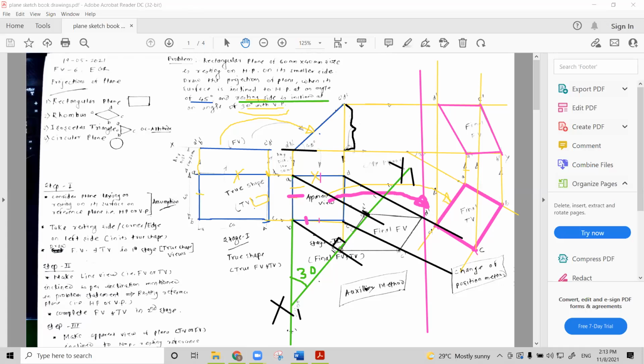So this is what the distance from this point to this point is, nothing but the distance, right? So this distance you have to take in a compass and draw those marks on this black line here, and wherever you get the points, finally you have to join all those points with a thick line, okay, and complete that